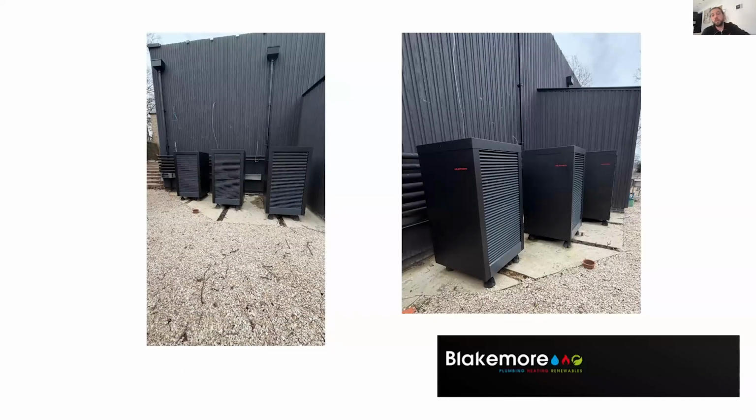So we fitted three 20 kilowatt Heliotherm R2 90 units. There were two 800 litre cylinders. We've got four 450 accumulators because we've had to size for the full house load. There's only four people living in this property, husband, wife, two young children. But he wanted to have full load covered for the full house, which made it challenging.